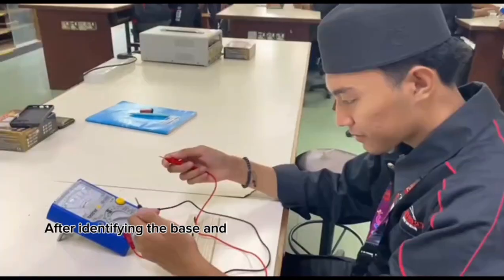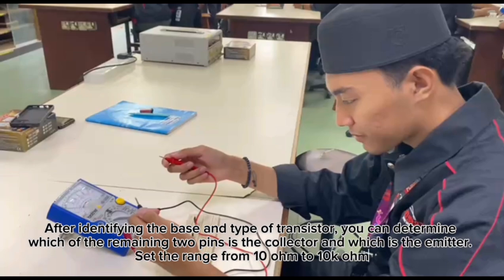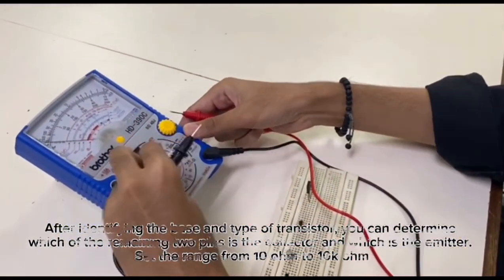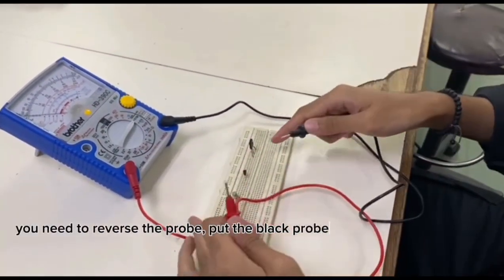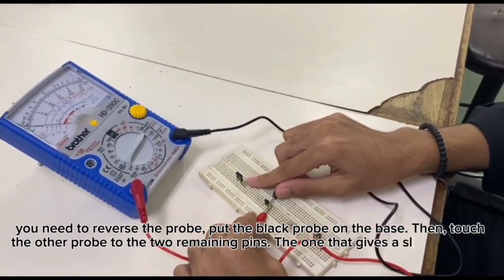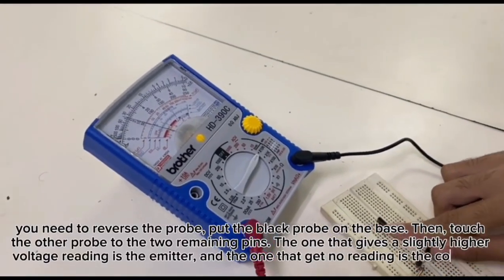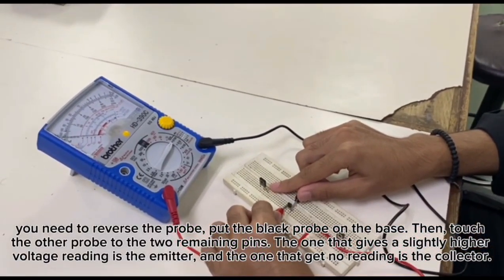After identifying the base and type of transistor, you can determine which of the remaining two pins is the collector and which is the emitter. Set the range from 10 ohm to 10k ohm. You need to reverse the probes. Put the black probe on the base, then touch the other probe to the two remaining pins. The one that gives a slightly higher voltage reading is the emitter, and the one that gets no reading is the collector.